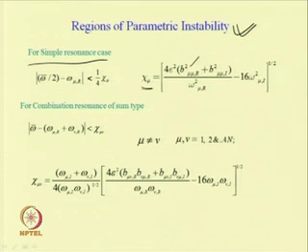This is the real part, this is the imaginary part, by omega square mu r minus 16 omega square mu I, all under the root. This is for the principal parametric resonance case. Here, omega bar by 2, it may be noted that the resonance will occur at a frequency twice that of the natural frequency. That is why one can take omega bar by 2 minus omega mu r, which for the transition curve will be equal to 1 by 4 x mu. So, by finding this mu value, one can plot the instability region.